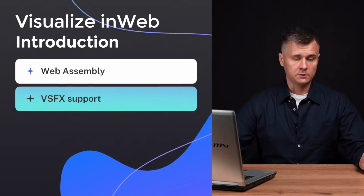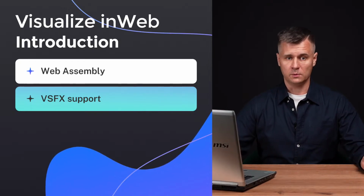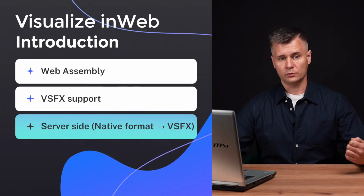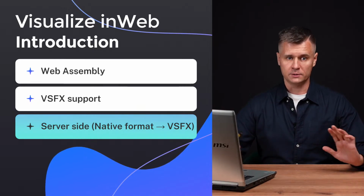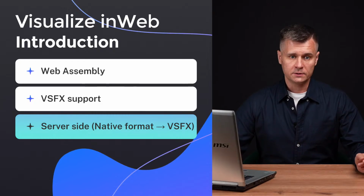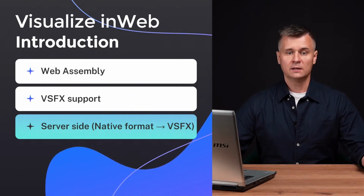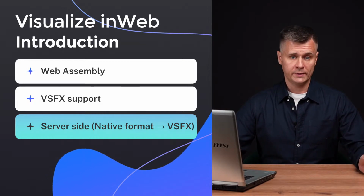And if it happens so that you can export data from native format to VSFX, you can work locally. But if you do not have this opportunity, or do not wish to force your clients to do so, or wish to help your client, just do not care about the formats, export, and etc., there is a server side that allows to export the native format, say Revit or IFC, to VSFX, transfer VSFX back to the client side, and then work with it.